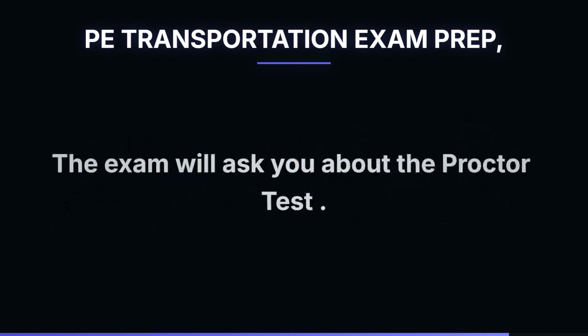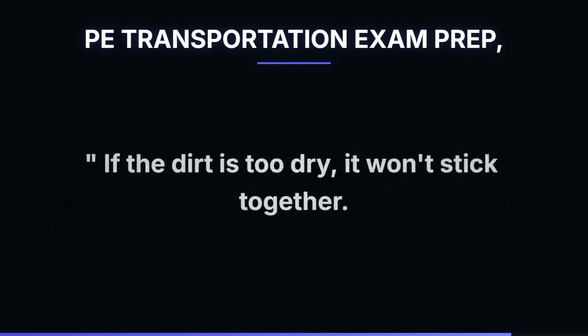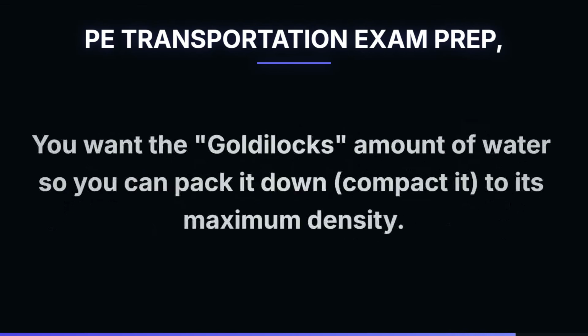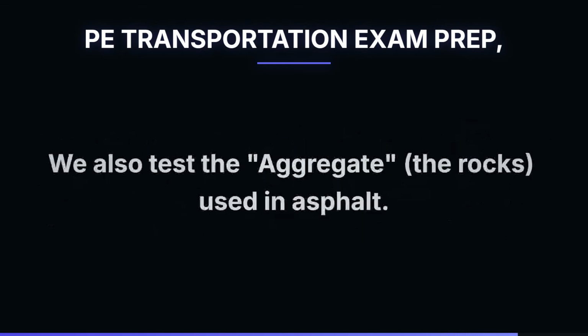The exam will ask you about the Proctor test. If the dirt is too dry, it won't stick together. If it is too wet, it becomes mud. You want the Goldilocks amount of water so you can pack it down, compact it, to its maximum density.